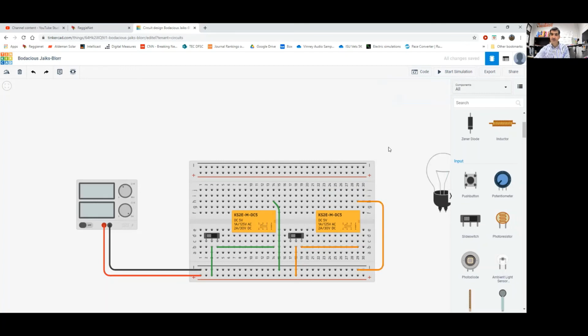Okay, that completes the first and second rungs of my OR logic gate circuit. And now I've got the third rung, which is the most complicated one. Let's look at the upper part of the third rung. I need to go from the power supply to the common of CR1A. It doesn't tell us whether it's CR1A1 or CR1A2, so I can use either side of the relay. I'm going to use the lower side just because it seems easier and closer.